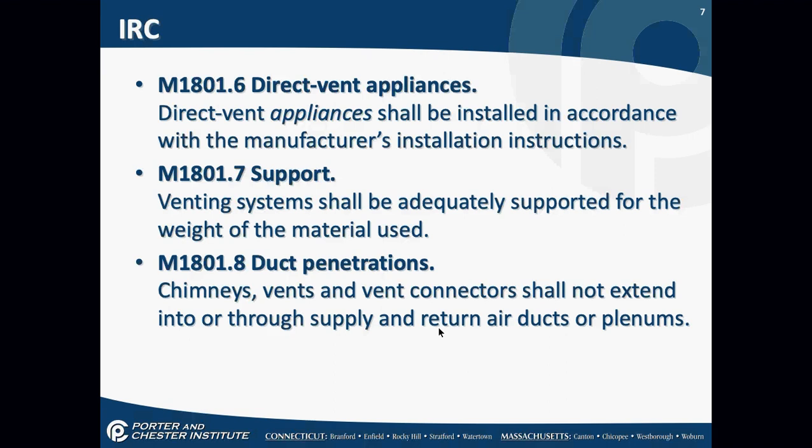You cannot run a chimney or a vent connector through supply and return air ducts. Believe it or not, somebody has done this. That's why it's in the code. There's been a supply or return air duct that someone decided to run a chimney directly through the center of. Can't do that, because if that leaks, the products of combustion that include carbon monoxide are spread through the building.